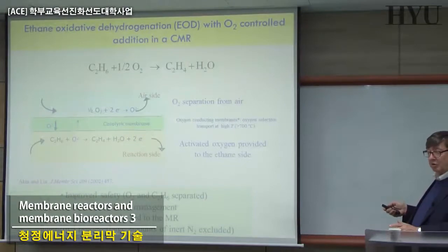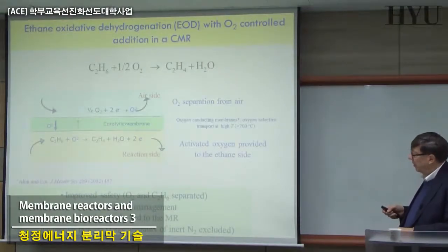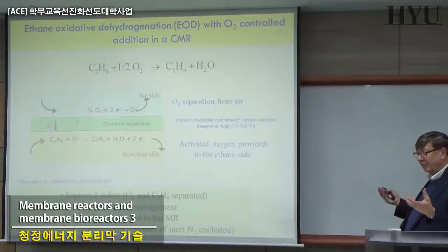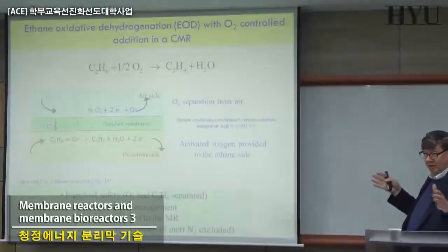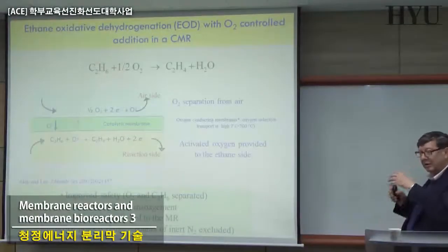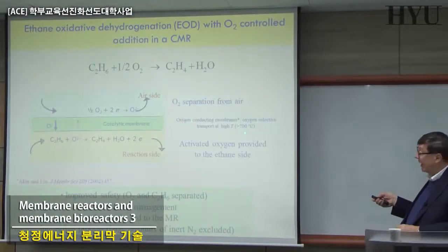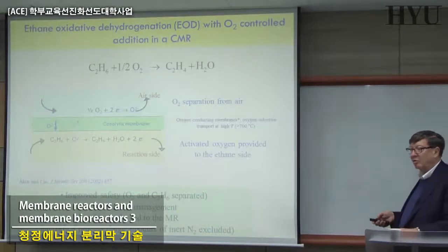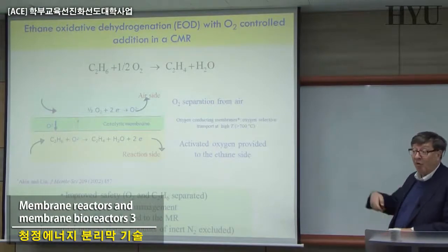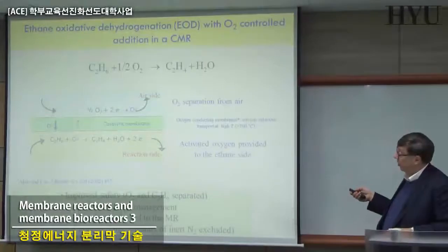And this high temperature is not a problem because of the energy involved, that's not a big problem, but because of the stability of the membrane and the production. This is a huge plant, not a small plant. And if you have to seal your membranes at temperatures higher than 700 degrees, it can be 800, 900 degrees, it is not so obvious how it can be done for a long-term installation, etc. But there is a lot of work in progress.